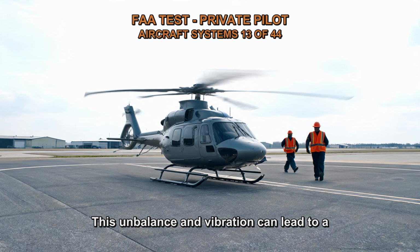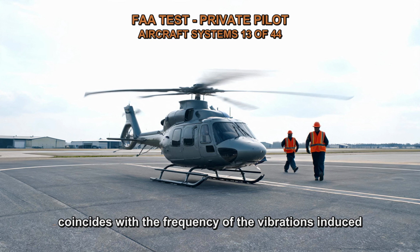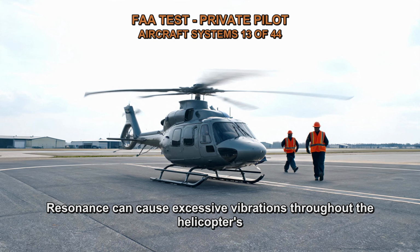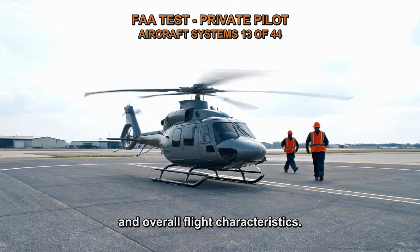This unbalance and vibration can lead to a resonance of the fuselage, which refers to a condition where the natural frequency of the fuselage coincides with the frequency of the vibrations induced by the landing gear impacts. Resonance can cause excessive vibrations throughout the helicopter's structure, which can be detrimental to its integrity and overall flight characteristics.